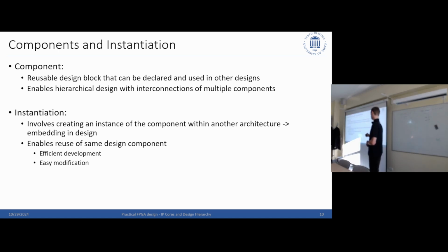And then you can basically have components within another architecture. Basically, this will allow you to pull in one design into another, and embed one design into another one. And then you can build from a lower level up to a higher one, which is quite nice. And this, of course, means I do not have to write my UART or my router or my FIFO every time. I can just always use the same thing. It's efficient and easy modification. Of course, you have to be careful: when you want to change one, it will change in all the places. But that's how libraries and everything are.